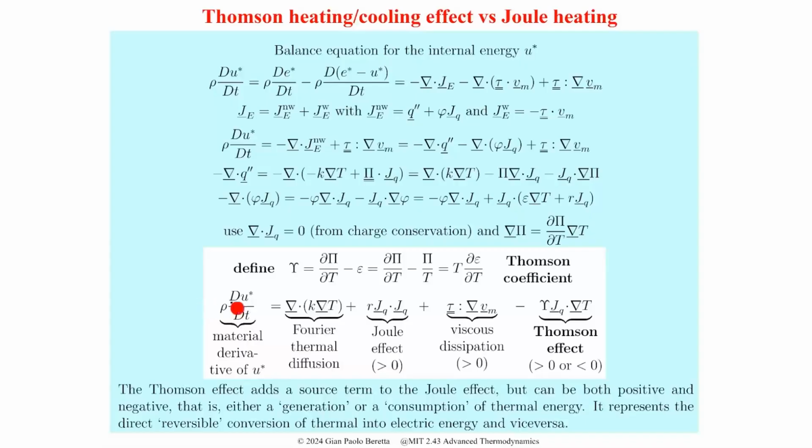So you should think of this as the equivalent of the Fourier law, Fourier equation of conduction. So this would be rho Cv times dT/dt, the temperature derivative. This is K times the Laplacian of the temperature, if K is independent of position, therefore of temperature.